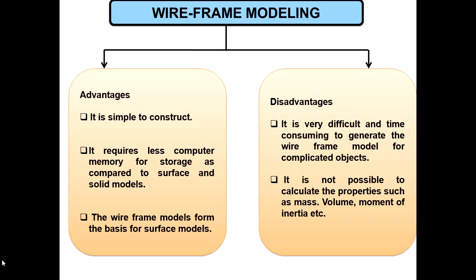Then some of the properties cannot be calculated with the help of this wireframe modeling, as it is not complete. It is constructed with the basic geometric entities. So we cannot calculate the mass, volume, and moment of inertia. These important properties are very difficult to calculate with the help of these wireframe entities.